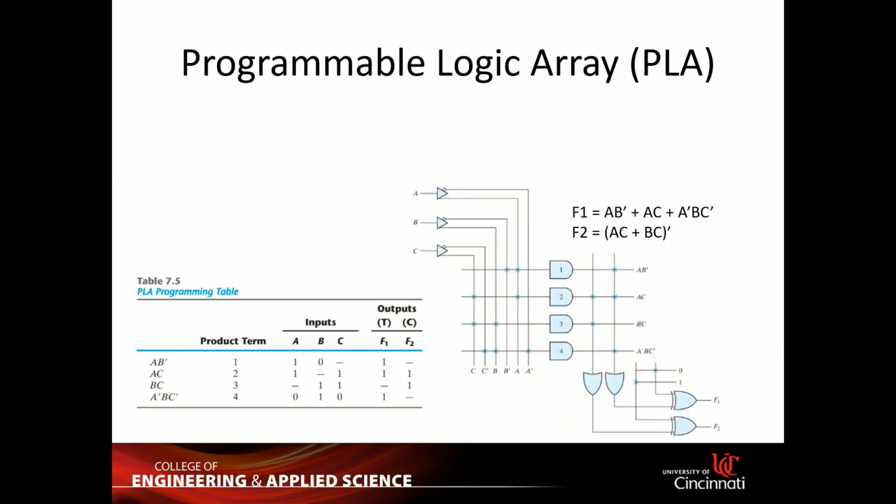Okay, final topic here, programmable logic array or PLA. And this is not the PLA material that you use for 3D printing, it's the programmable logic array. So the concept is very similar to ROM because you will have an array, then you use fuses, you burn the fuses, you can program 0 or 1 based on the fuses itself.